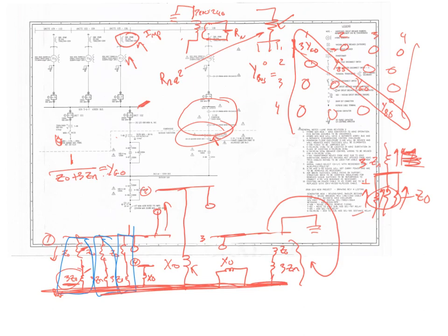If it's a three-phase fault, there's no resistance, right? All three phases are connected together. So how would you calculate the fault current at a three-phase fault there? Would you just take the power divided by the voltage? What power? Whatever power's supposed to be flowing through that bus? Actually, fault currents have nothing to do with power. You need the voltage and something else.